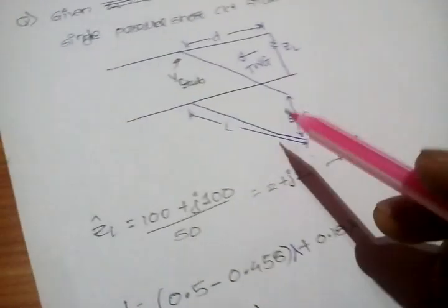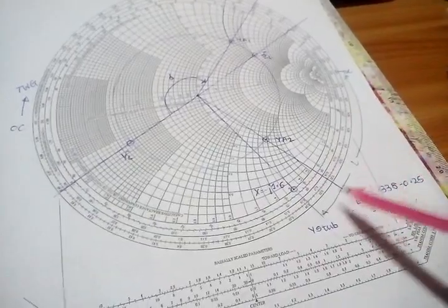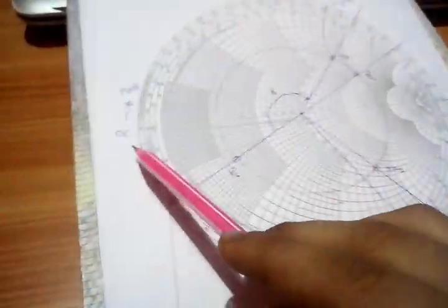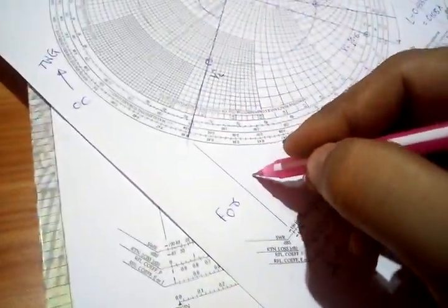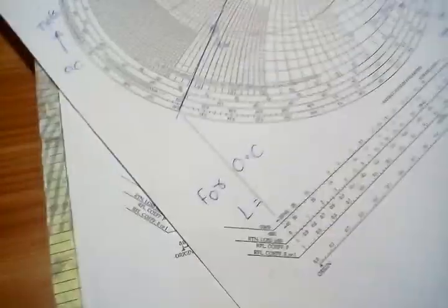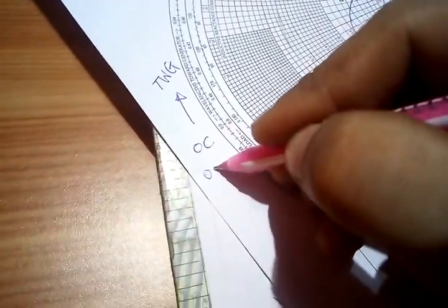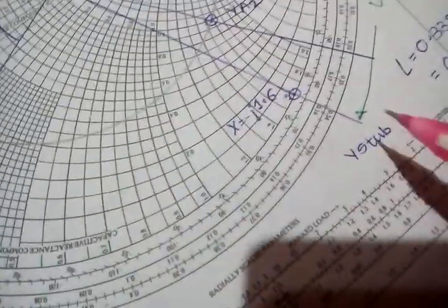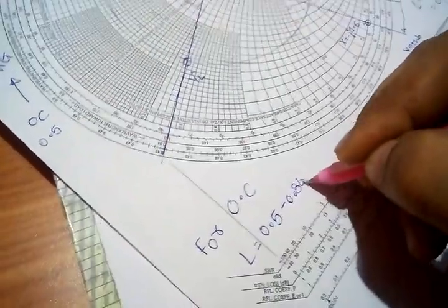So what we should do if we get a parallel open circuit, if this becomes open circuit? Nothing to worry about. The distance we calculated from the short circuit, we need to calculate from the open circuit. So I'll just write it for you. For open circuit the length would be 0.5 at this point, as you know, and this is 0.34, so minus 0.34.